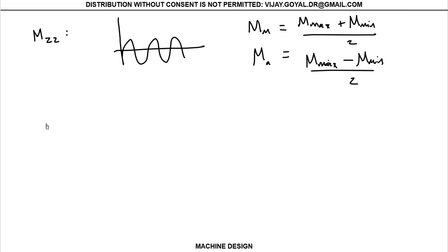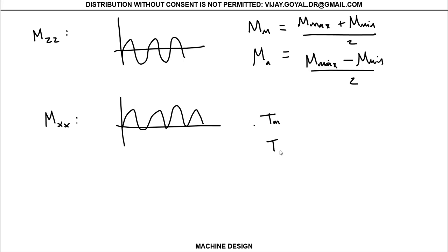Okay? Then you can also have your torque. Remember, these are the values that you get from your plots, from your shear moment diagram and load diagrams that we did in your homework 1 and 2. With that load, we actually do have some fluctuation. So you can have a torque mean and a torque alternate, which equals torque max minus torque minimum divided by 2.